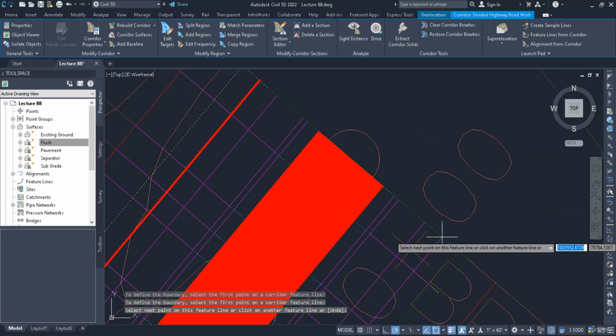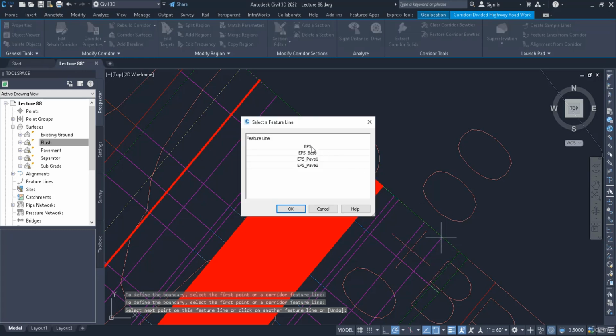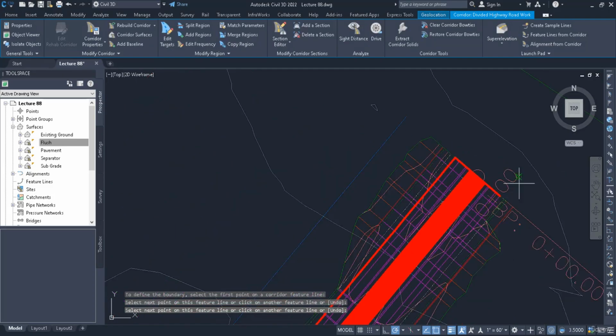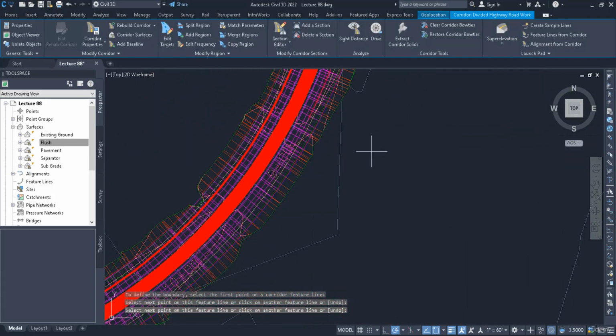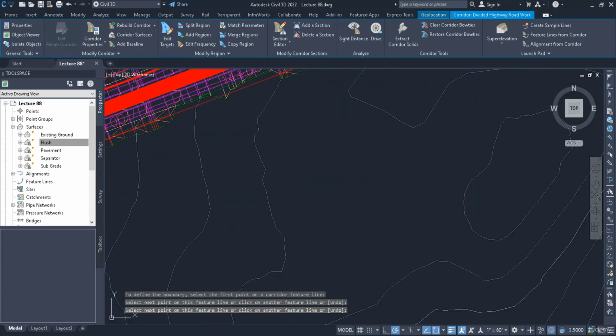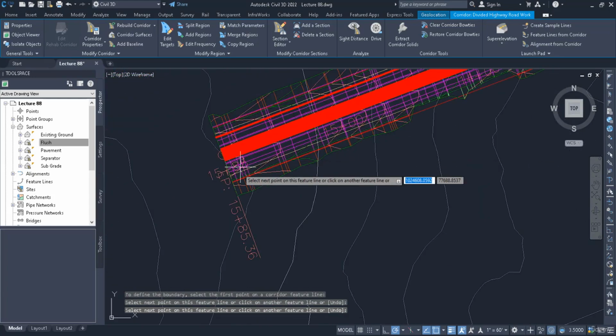We have to go towards the opposite side as it is a mirror image. So the fourth purple line, or the magenta line, we have to select it, and press the left mouse button. Again, we have to go for the EPS, press OK, and now we have to complete it by moving all the way to the end. A red line would be following to show the path.